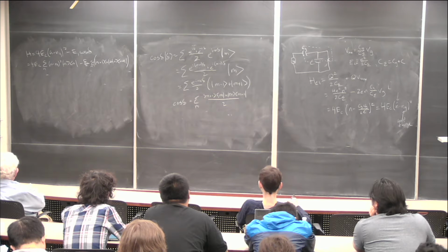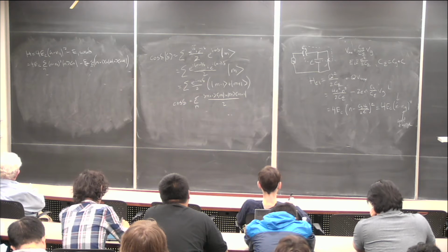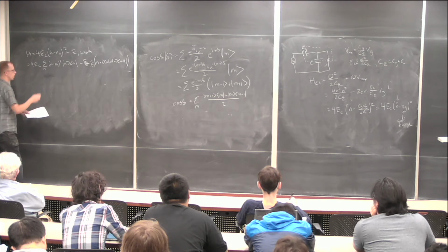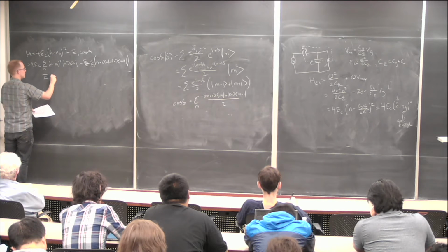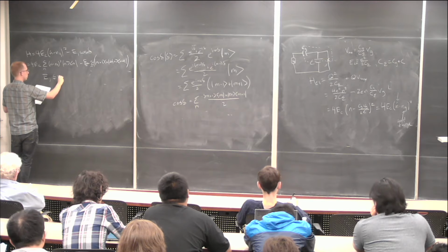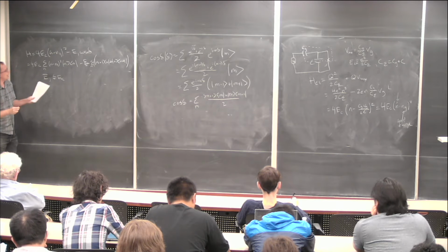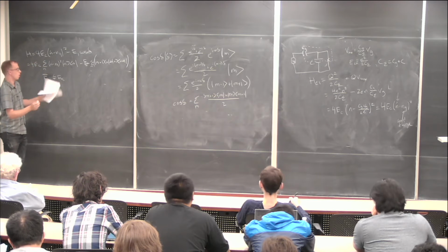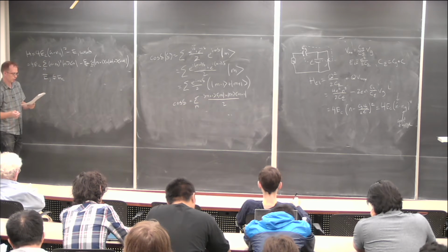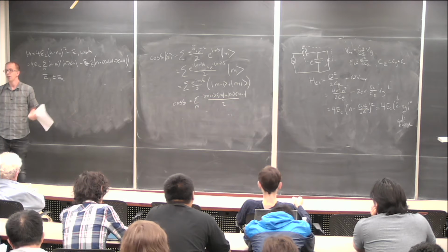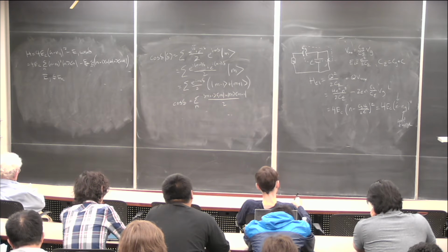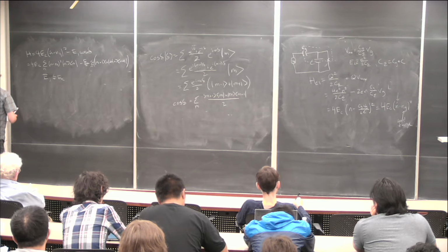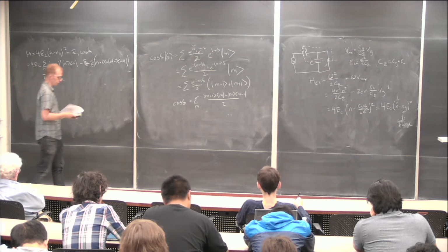We like to work in this sort of charge space, because in the limit that these early experiments worked on, E_J is less than or approximately equal to E_C, and the contributions from this term were mostly dwarfed by the contributions from the electrostatic term, so charge winds up being essentially a good quantum number almost anywhere in this circuit, and so we like this charge basis.